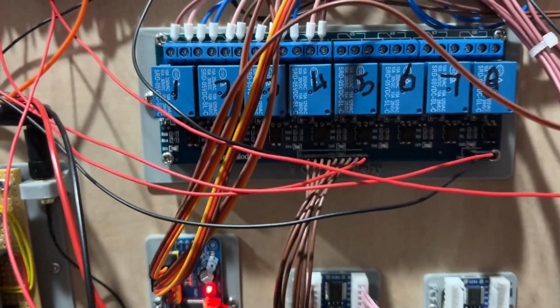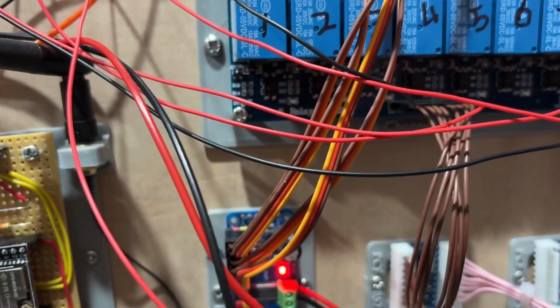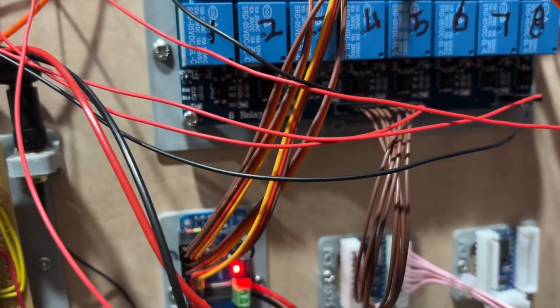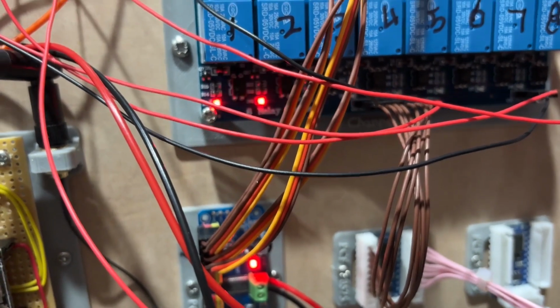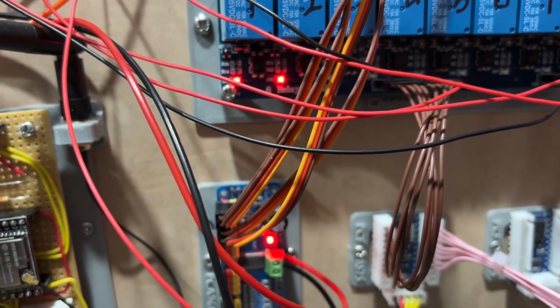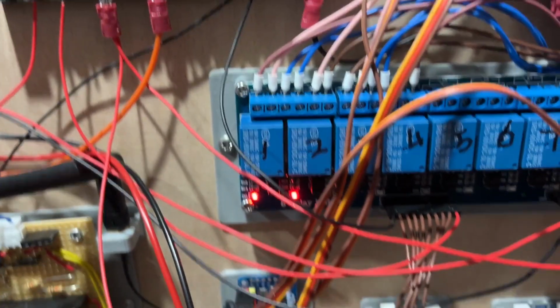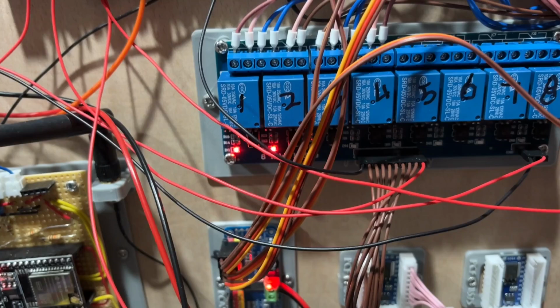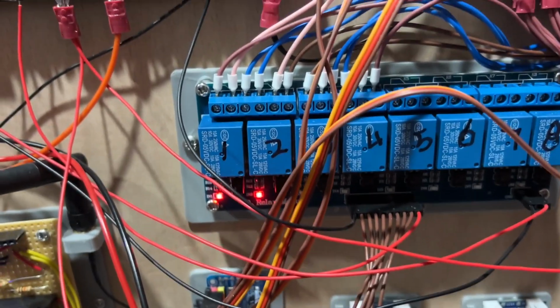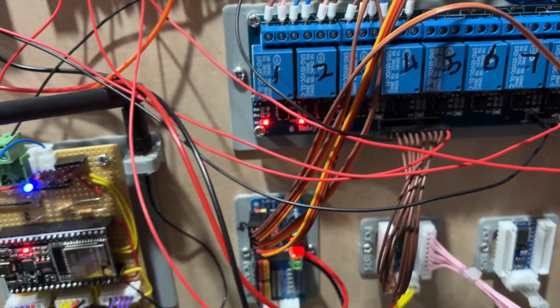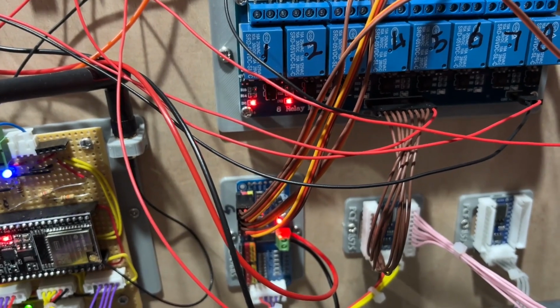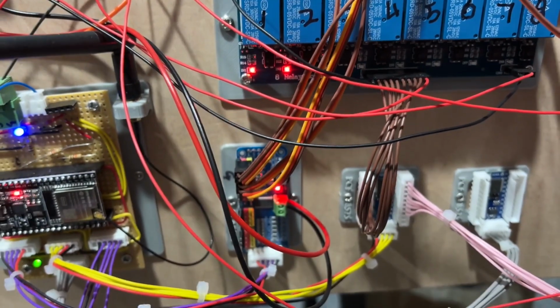There we are. So some went out. If I come back over here, do that again. There we are. See two little red lights on. These are wired so that if the power to the relay fails, the frog is set for straight ahead running. And that was done because originally when I set this up, the relays existed, but the control logic didn't. So we got around that.